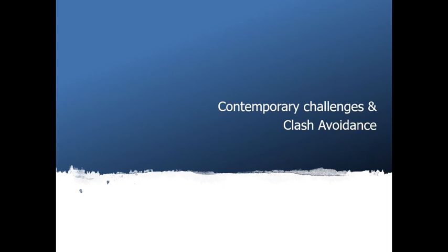With that in mind, the BIM coordinator will have fewer clashes to resolve, because if you apply a clash avoidance strategy, and you've got different strategies to have in place, you're avoiding as many clashes as possible. So you're resolving clashes as you go forward. Okay, so this is clash avoidance.